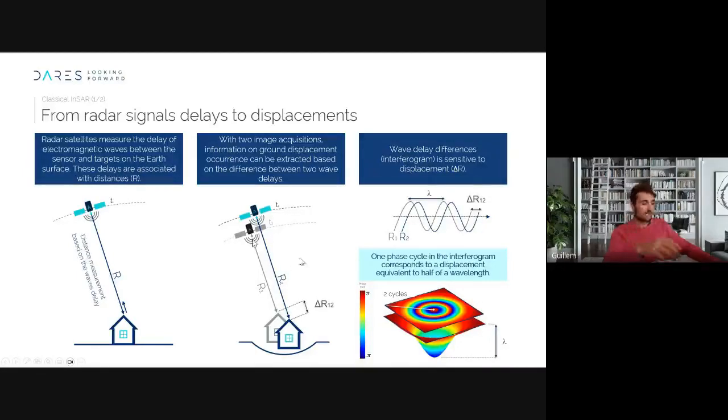If we are working, for example, with a Sentinel-1 satellite, we will have another image of the same area, for example, if we are in Europe, after 12 days. So I will get the SAR image after 12 days, I will get rid of the amplitude, I will take the phase, and then I will subtract both phase images, which have a difference of 12 days.